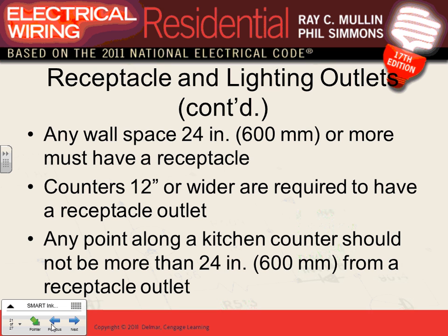Now there are tiny little rules, Aaron, that we use. You have a wall in a habitable room, and that wall is 2 feet or more. I call it the 2-foot rule. A tiny little wall between 2 doors, 2 feet or more, you need 1 receptacle. Can you guys write yourself a note? In any habitable space, you need 1 receptacle.